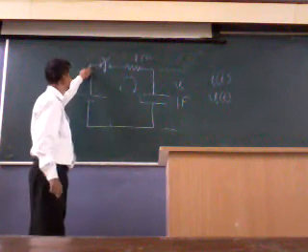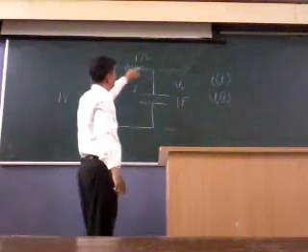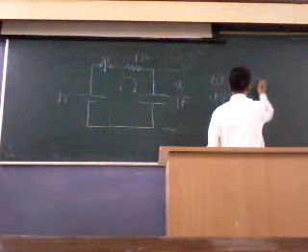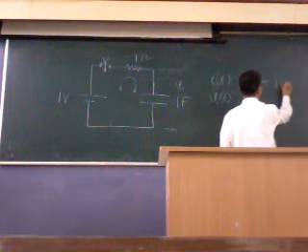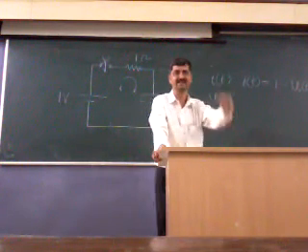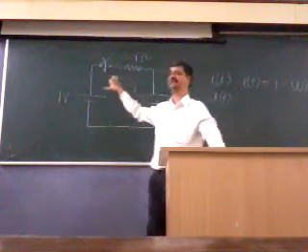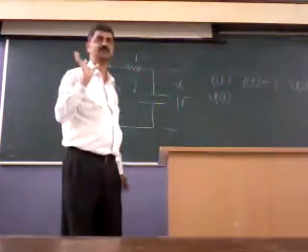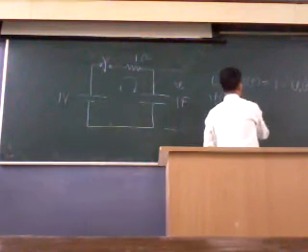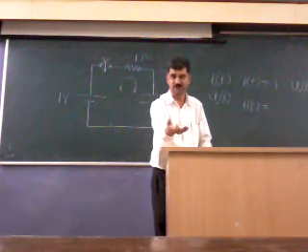This will be 1, from t equal to 0 onwards. It would be equal to 1 minus Vo divided by 1, correct? For the present values, it is 1 minus Vo(t). And for the capacitor now, what should it be? It is C dVo(t) by dt.